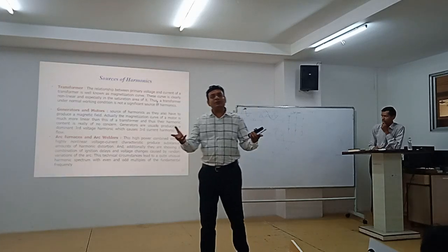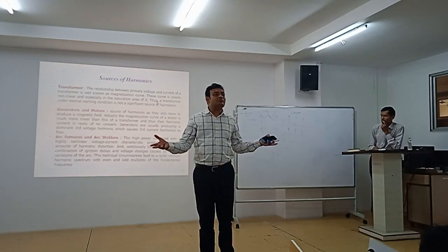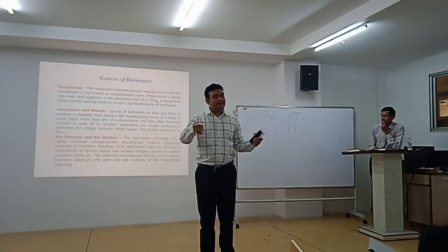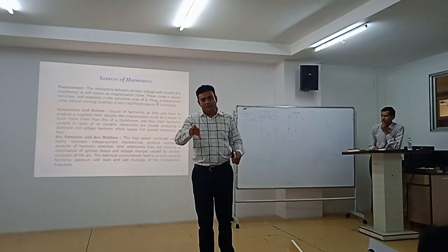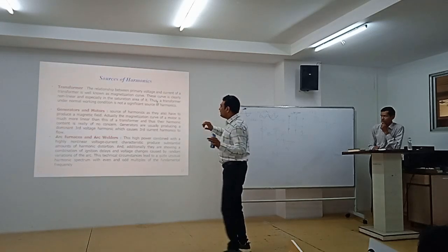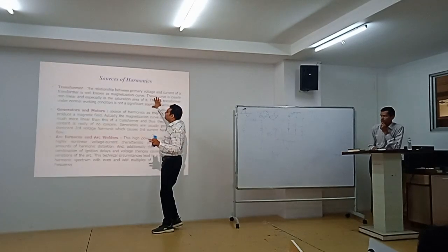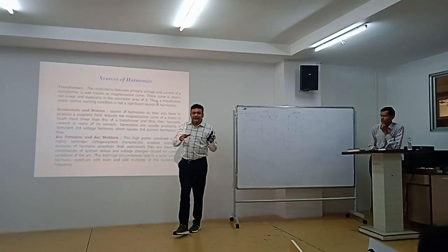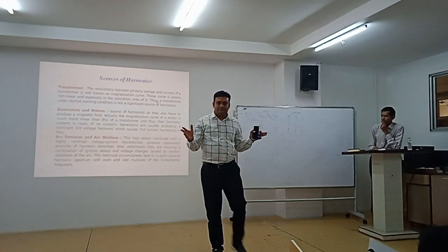Transformer. Transformer, if we consider it a linear load, so why does it become a source of harmonics? Magnetizing, starting, industrial. Yes, industrial magnetization. So transformer at maximum saturation region will act as a non-linear load, right, and produces harmonics, right?